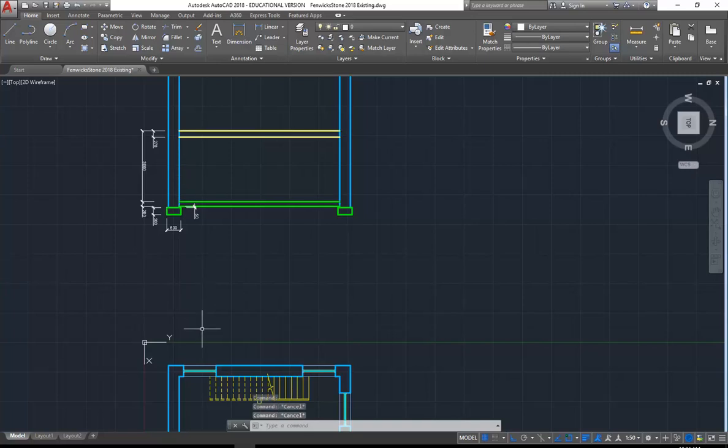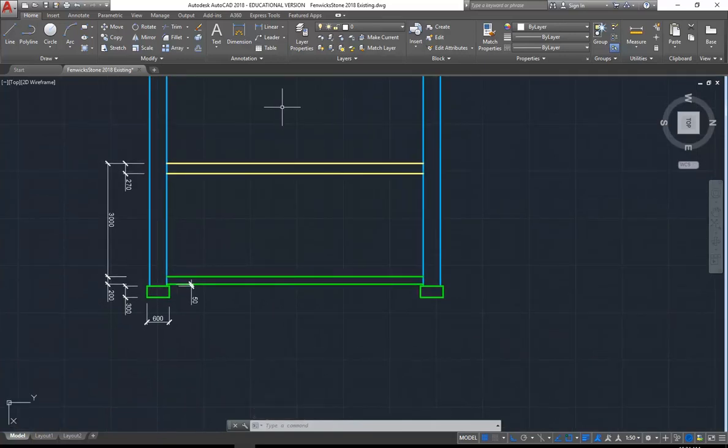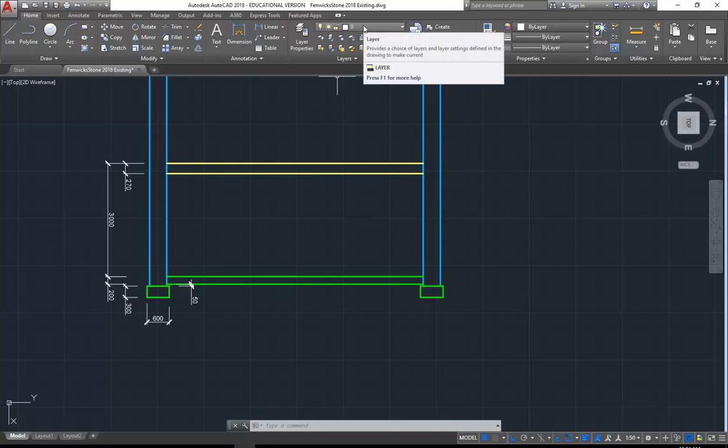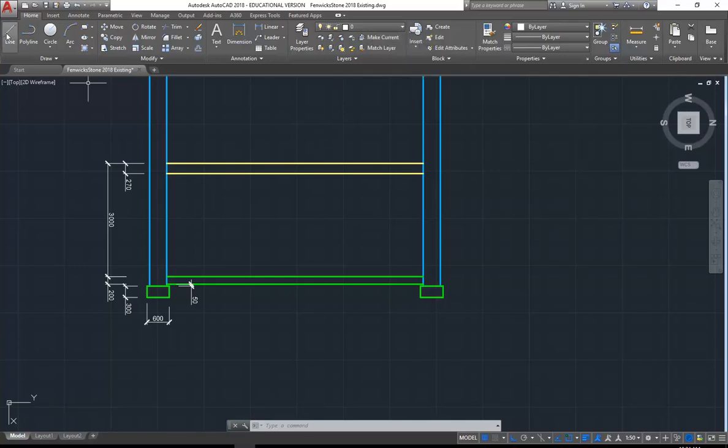Okay, so to set out my risers, I'm going to draw an extra line. You can see there, I've just gone back to layer 0, so it's clear to everyone that I'm drawing a construction line. This is a line that I'm not going to keep. So with the line tool, maybe I'll just keep it simple and draw from the midpoint of this floor to the midpoint of the floor above. So that's like a measuring rod that I'm using to measure the height between those two floors.